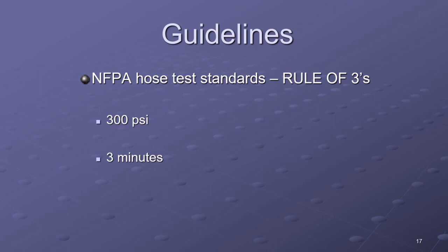And generally, we don't have a lot of places where you can do straight hose lays of more than 300 feet. But if you could put 500 feet out there, you can test all 5 pieces. It's not regulated to 3 lengths of hose any longer, and even NFPA has changed that. From a hydraulic theory standpoint, the pressure is equal in all directions.